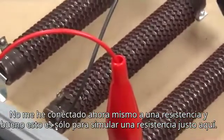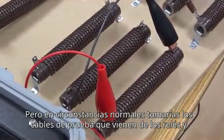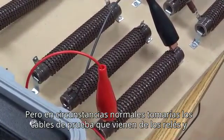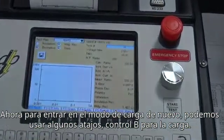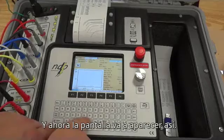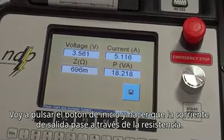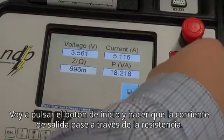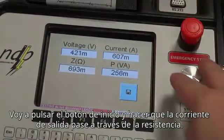I have it hooked up right now to a resistance, and this is just to simulate, just a resistance right here. But in normal circumstances, you would take the test leads coming from the relays and hook them up to these two test leads. Now, to go into the burden mode, again, we can use some shortcuts. Control B for burden, and now the screen is going to appear like this. I'm just going to press start and have the output current go through the resistance.